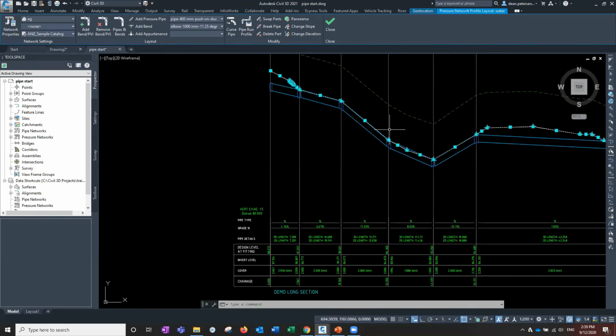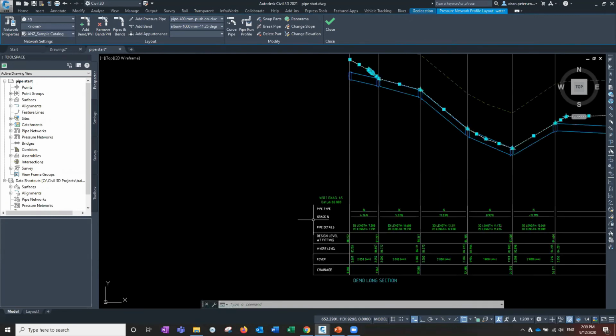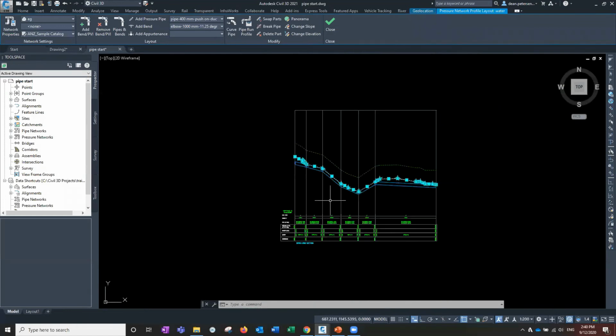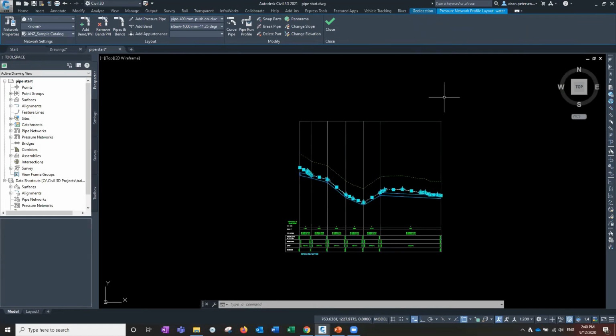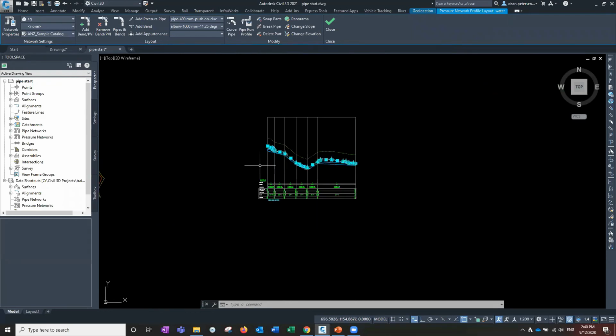You do have to be a little bit careful playing around with these things. I have had them lose association, but as an up-and-coming feature, it's pretty cool. What I'd like, and I do have a ticket out with Autodesk at the moment, is to have the pipe type, the actual diameters and type of pipe, able to be reported in the bands as well. But also, we could have another band up the top here, or wherever you wanted it, showing the fitting type as well, what angle the bends are, would be nice too.